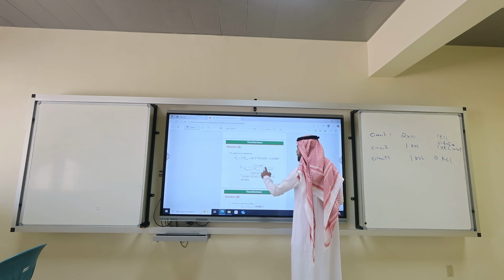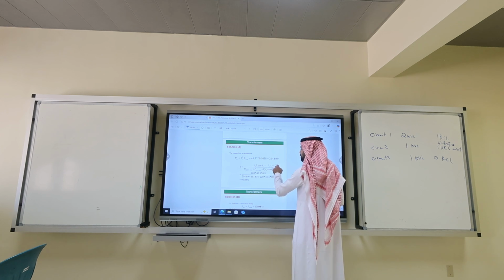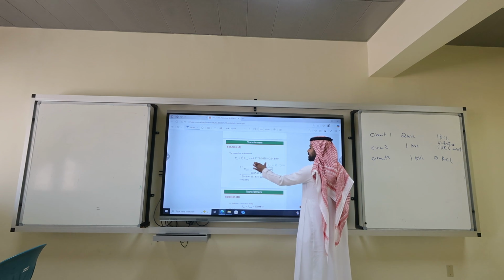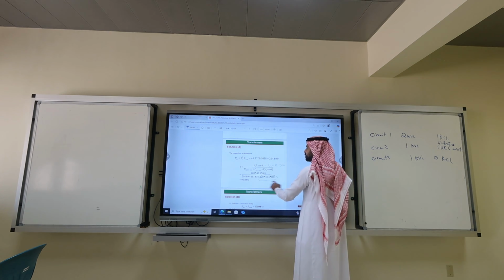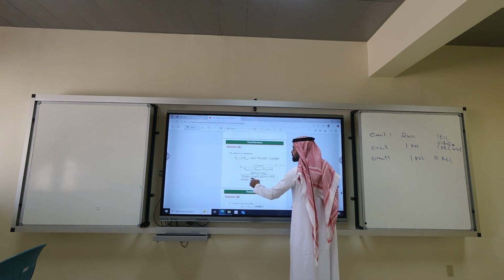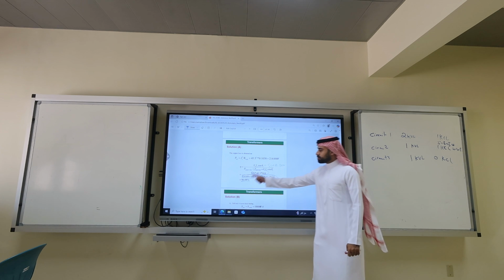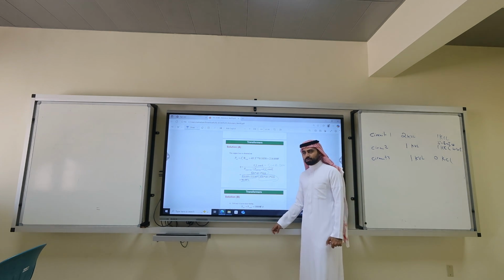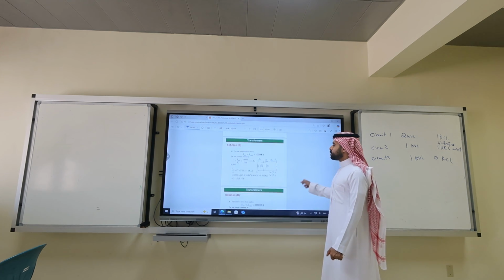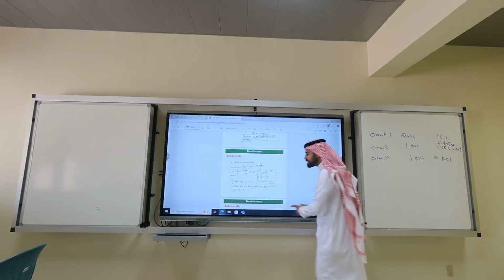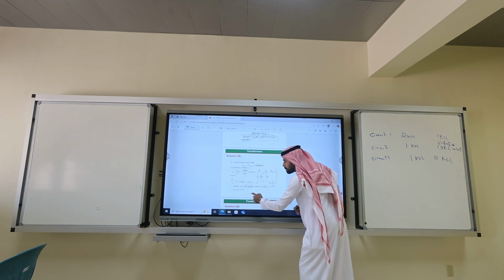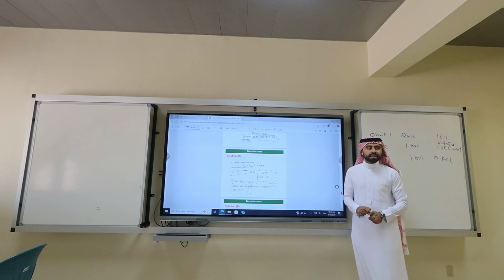What is the efficiency? You can use this equation, or you can use S cosine theta, which is what? 8 kilowatt. So 8 kilowatt here, 8 kilowatt here, plus the losses. Is this a good, bad or average transformer? Average. Is the engineer pass or not pass? Pass, okay? If you do part B, the only difference is this angle becomes plus 36 because it's leading.